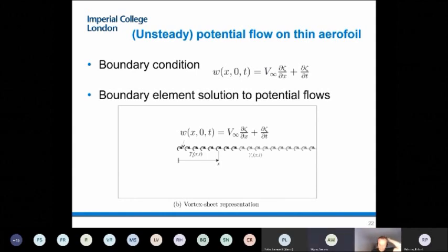Yeah, carry on. Okay. So what we do then is to basically superimpose the singularity solutions all the way, and of course this becomes an unknown. So the problem becomes, what is the distribution of circulation, or vorticity, that I put all the way through my boundaries, such that the flow they generate satisfies the Laplace equation by choice, which they do, and second, the boundary conditions. We don't need to do anything at infinity because the choice of circulation that decays with distance means at infinity the velocity goes to 0, and then you just superimpose the constant flow speed from the inflow. So that one is automatically satisfied by this choice.